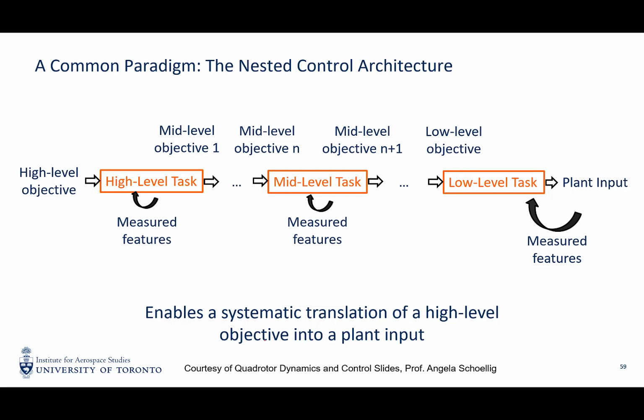The reason is that a quadrotor is an under-actuated system. It's not fully actuated. So we have to control the attitude in order to control the motion in the translational channel. Usually the lowest level of control is how to stabilize the attitude such that we can point the lift direction anywhere we want.